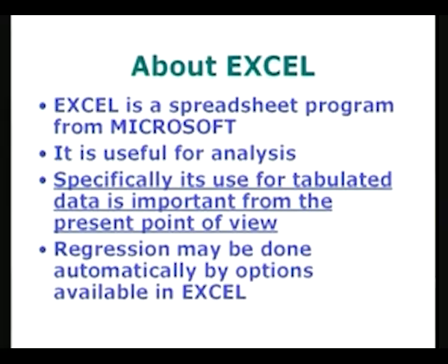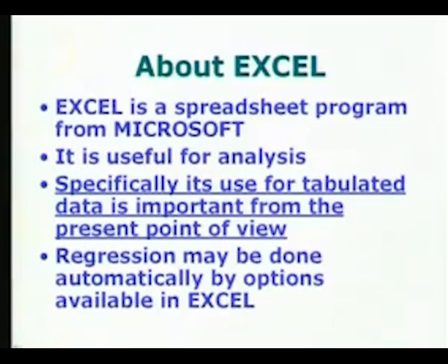The advantage of the Excel spreadsheet program is that regression may be done automatically by using the options available in Excel. What I am going to do is to show how Excel can be used for performing a linear regression by taking a specific example, and I will indicate the steps involved in doing this analysis. I will also indicate how all the statistical parameters can be automatically obtained using Excel.